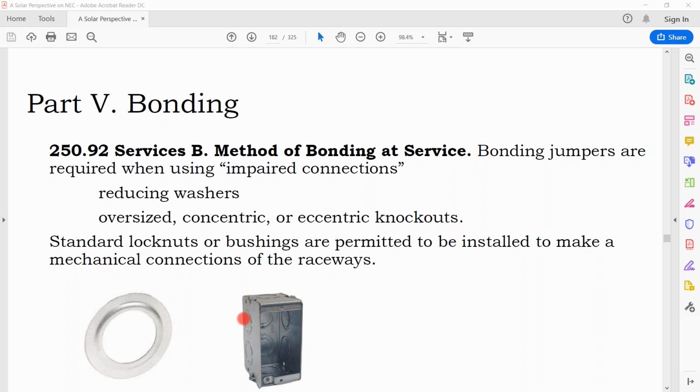They have these knockout rings on them, for a 3/4 inch conduit, for 1-inch conduit, and often they're various sizes, and so you have a small hole and a large hole, and when you're doing your design, you're like, well, which is the best to use? If I have 3/4 inch conduit, do I go into the 3/4 inch hole, or do I knock out the 3/4 inch hole that's inside the 1-inch hole?